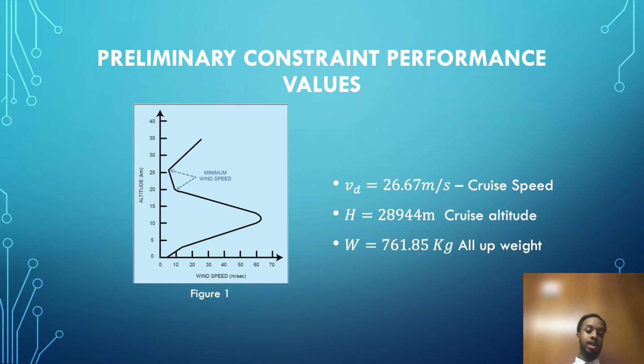The cruise altitude tends to be chosen between 15 and 30 kilometers for several reasons. First of all, it takes place well above the civil aviation airspace, leading to an easy operation of the UAV, as well as presumably an easy certification. Now, a high cruising altitude furthermore leads to wider area coverage, which is much easier for when the military are conducting their missions. Now, given the factors I had to use to calculate my wing height, there was another reason for adopting this chosen cruise altitude.